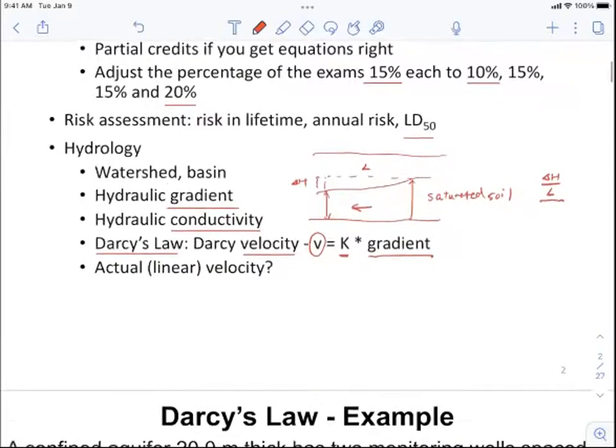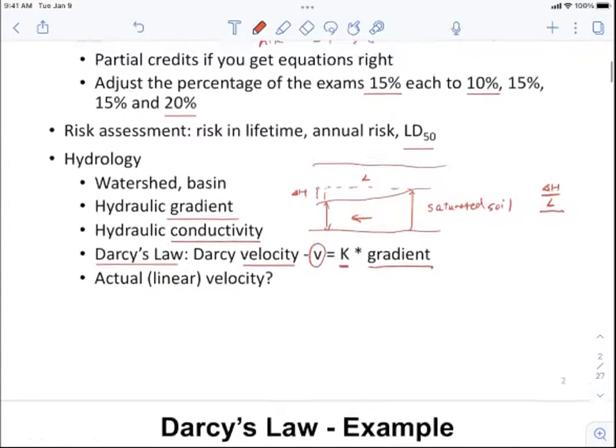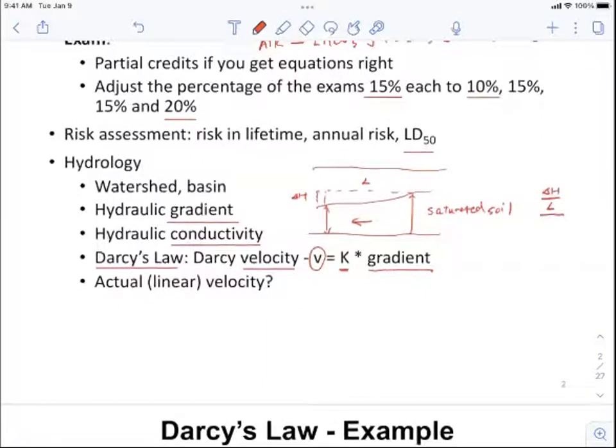After we know the average velocity, people also care about the actual velocity of water in there. If you have a medium, say a tube, where the water is flowing this way, then the average velocity is just the actual velocity. But if you have soil that's packed with sand particles, the water is not going to flow anywhere; it's only able to flow through the porous part.